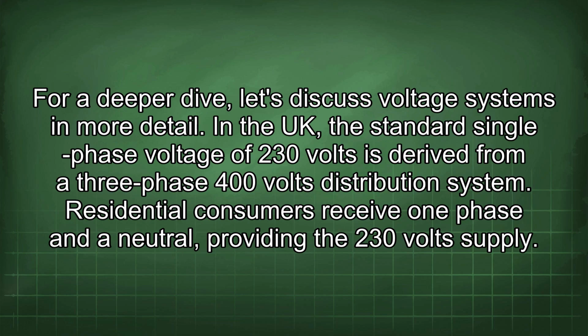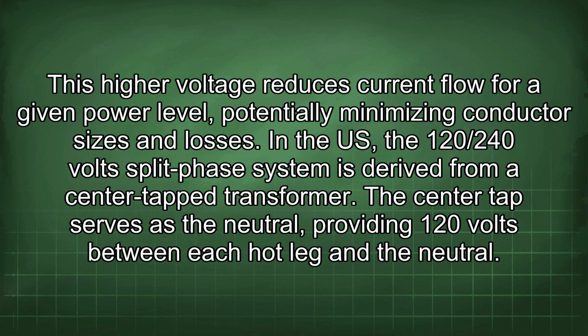In the UK, the standard single-phase voltage of 230 volts is derived from a three-phase 400 volts distribution system. Residential consumers receive one phase and a neutral, providing the 230 volts supply. This higher voltage reduces current flow for a given power level, potentially minimizing conductor sizes and losses.